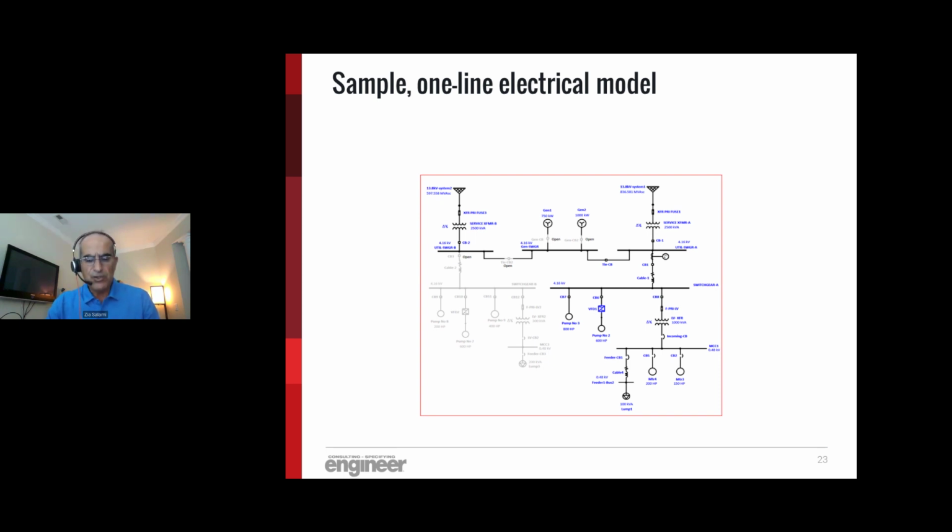Now, let's look at what we want on this one here. Let's just emphasize switchgear A. Switchgear A has a relay, an upstream relay, protecting not only the cable and the continuous amps of the switchgear, and of course it has to be coordinated with the fuse downstream.